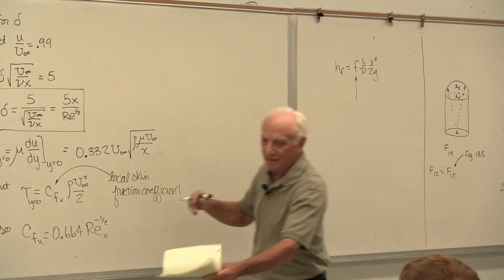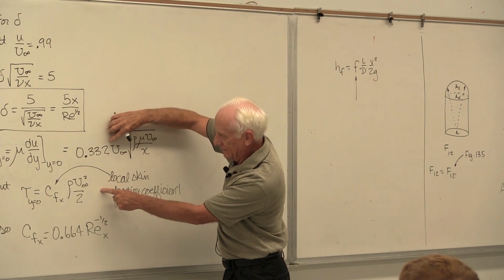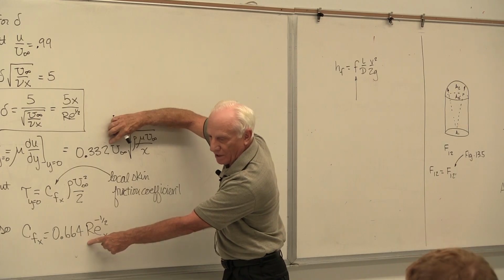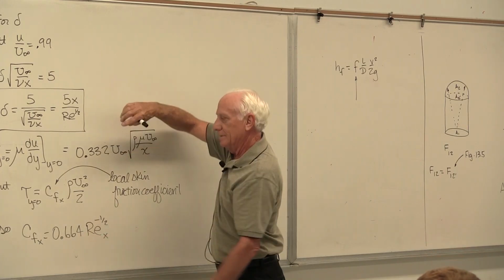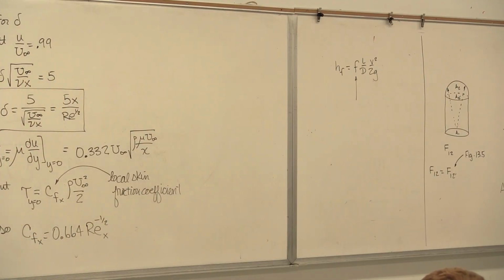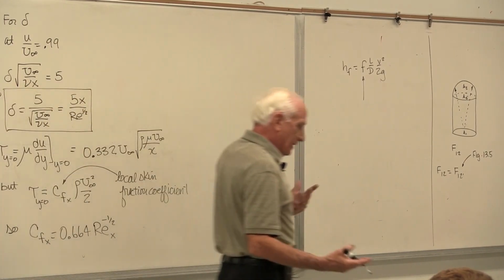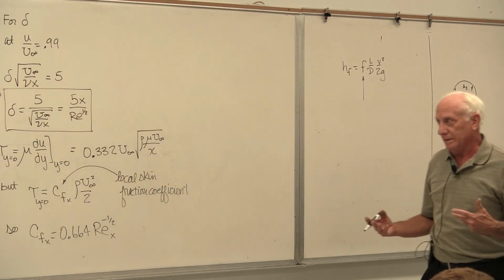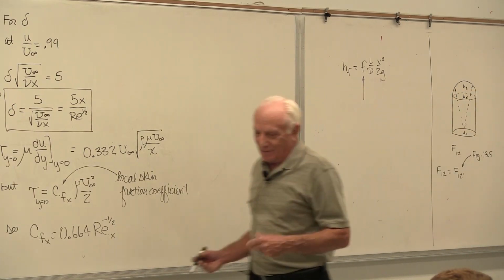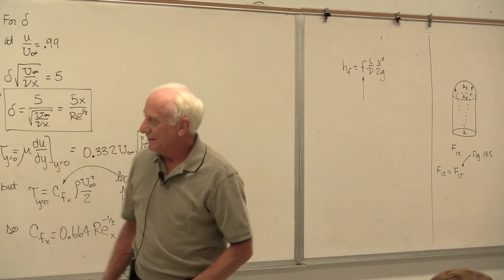So we take these two equations, we equate them. See the 2 right there? See the 3, 3, 2? There it is, 6, 6, 4. And so this is how in ME312 we found the skin friction on the surface over there. If you want to integrate that, multiply it by an area, you're going to get the drag force on the plate. Okay, ME312, one more time. So that's where we kind of ended up to start off with fluid mechanics.